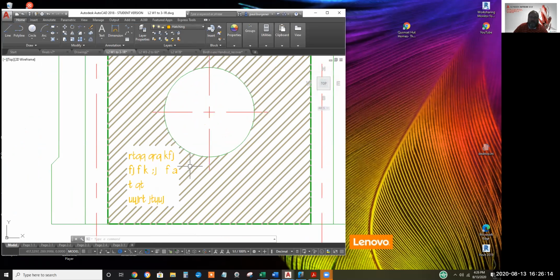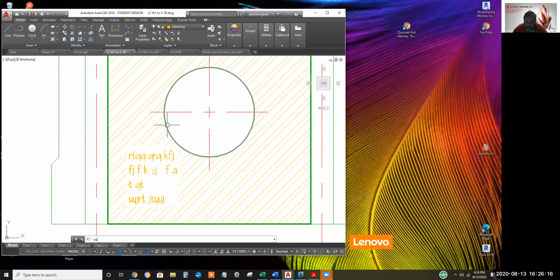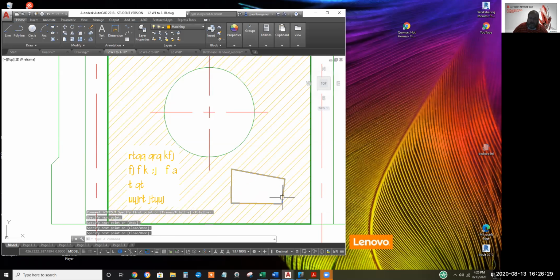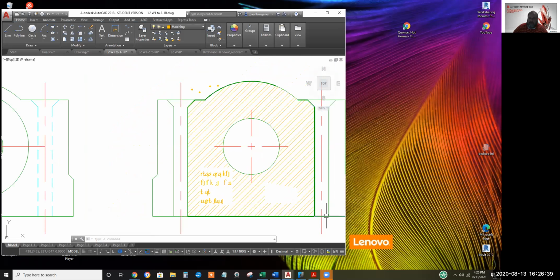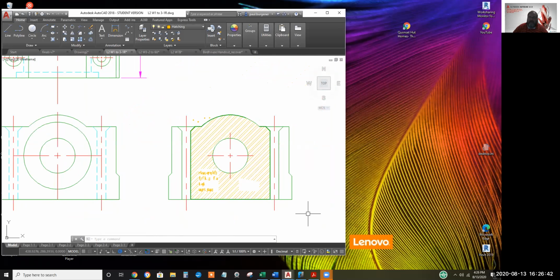Before this there's another way, there's something called a wipeout. WIPEOUT, enter. I've done this a few times. I'm not proud of it. But the wipeout will kind of put a cloak of invisibility over an area. Oh, that's cool. Ain't it though? This is one of those cheat steps that when you hear the bell of the elevator or the client coming on the floor of your building, might be the last minute.